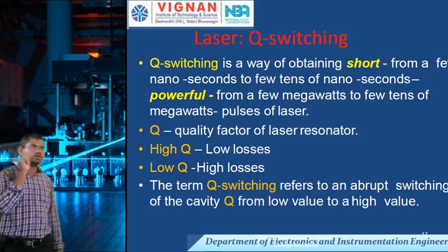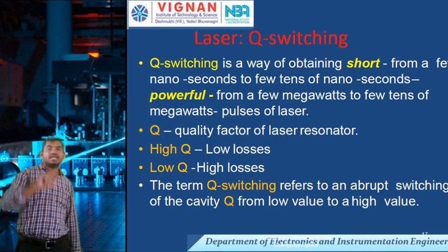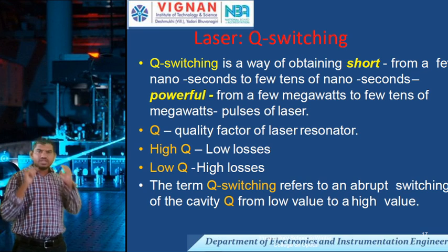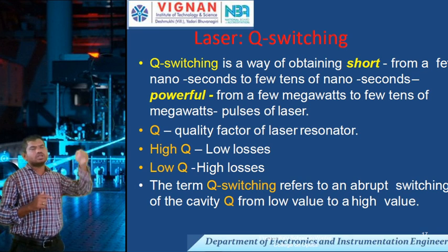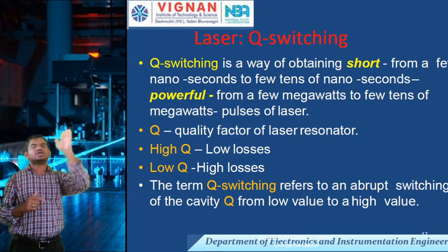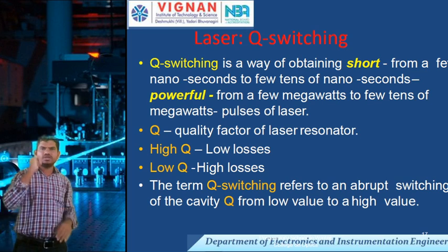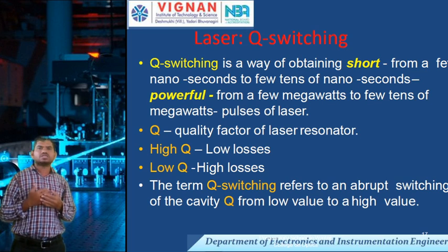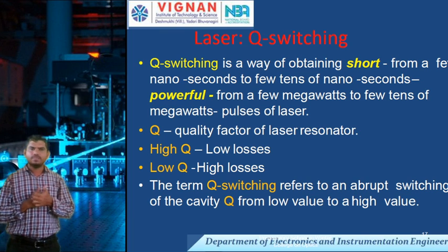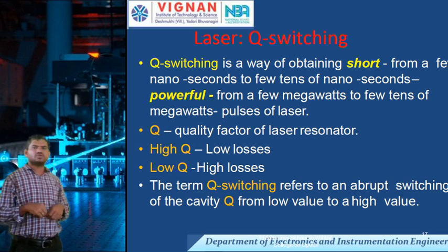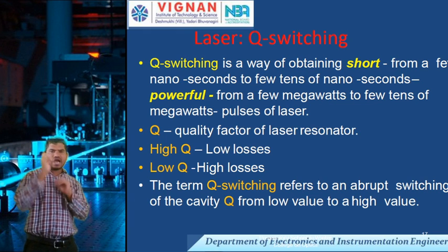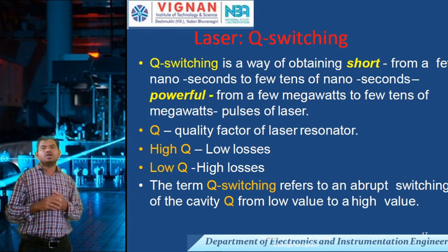How can we say longer distances? Because the losses are very low. When the quality factor is high, the losses are very low. If the quality factor is low, the losses are more, and we can't transmit the laser light over longer distances. That's why the quality factor can play a very important role in laser applications. The term Q switching refers to an abrupt switching of the cavity Q